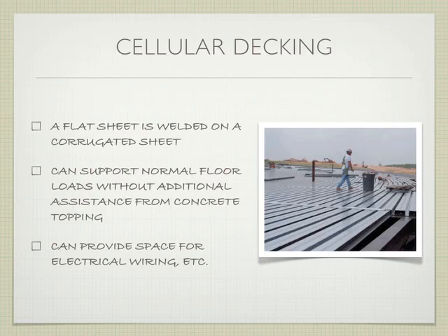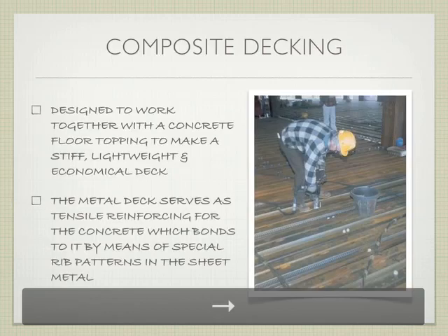There's a really good example of cellular decking that's used out in the San Ramon area. There's an AT&T building out there that was built a long time ago. I think 70s. I don't know the exact date, but they built it on a system like this, right? Specifically so that when they reconfigured the space inside the building, they could run new wires and adjust where the wires went because they had all these raceways to be able to pull the wires, right? So it ends up being an advantage if you're trying to work with the space and reuse it and change how it's used, right? So that's certainly a positive, right?